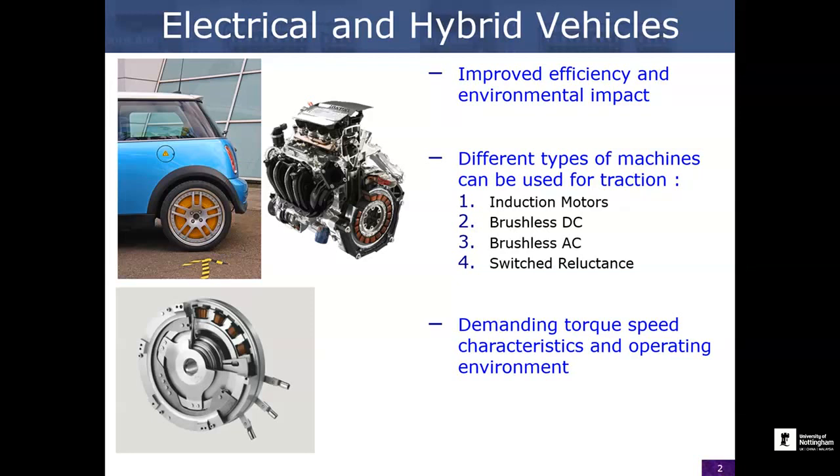If you move your electrical machine into a different place, if you put it into the engine compartment, you just end up with a different set of challenges. It's no longer exposed directly to the road, it has quite a lot of protection from the suspension, but you're sticking it into an environment where the ambient temperature is close on 100 degrees. You're sticking it in there with all the heat, with the mechanical vibration, with all the grease, with the risk of cross-contamination from hybrids with petrol. There's all kinds of challenges.